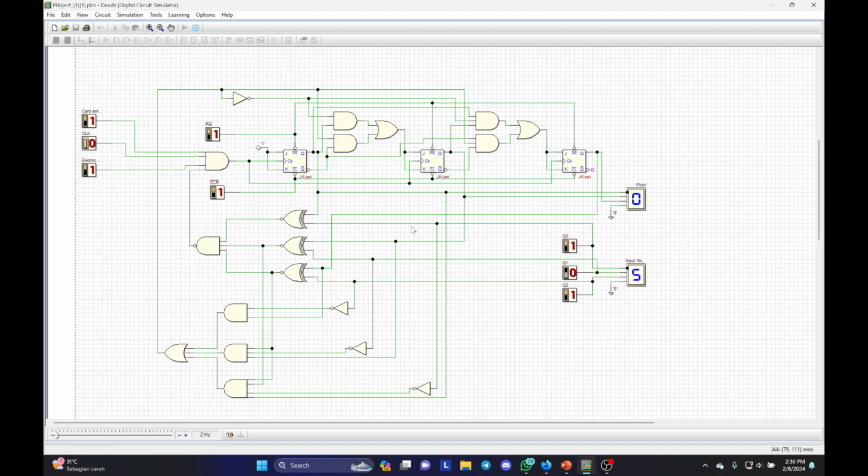Okay, so section B, the inputted floor, is greater than section A, the current floor that the lift is at right now, so the comparator in section C will output 0, essentially telling the lift to go up.